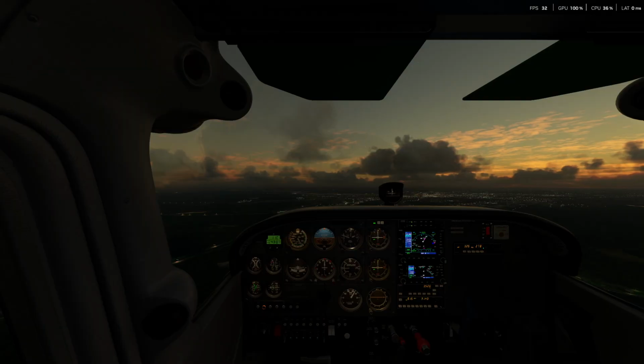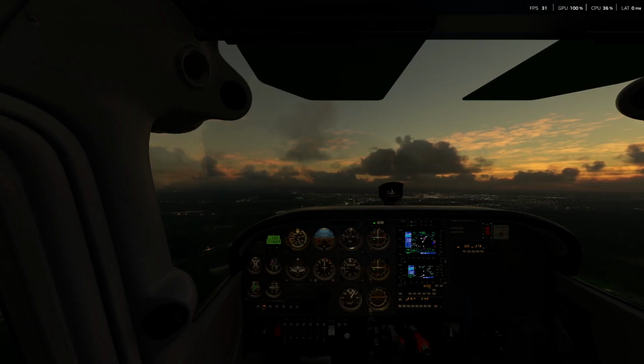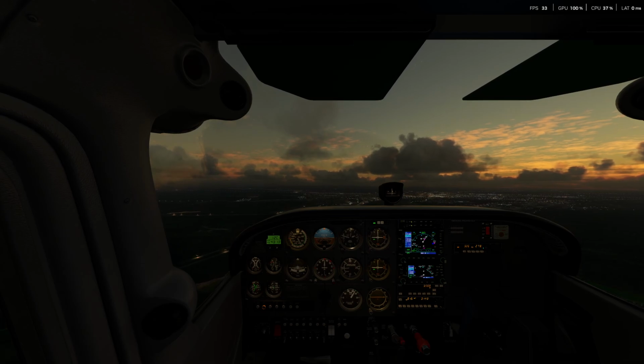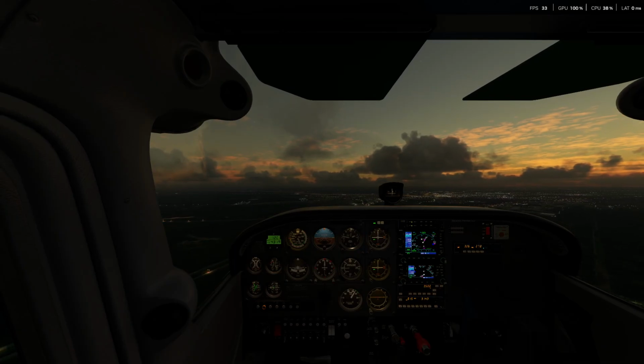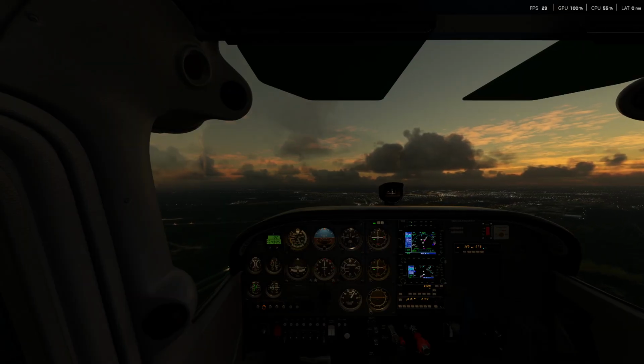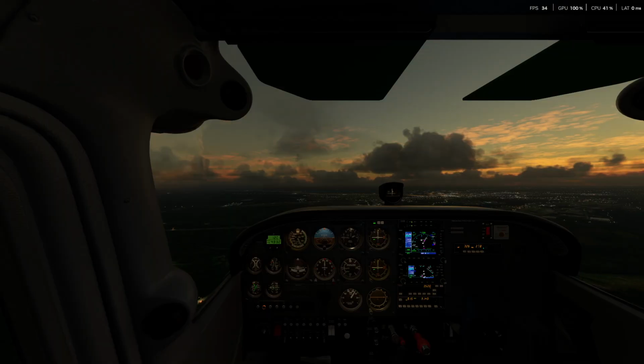You should be increasing the throttle just a little bit to increase the RPM. Basically, you want to make sure that everything's still working and that you still have that power available. The last thing you want is to get down low to the ground and not have that power there to keep it flying. So it's always good to do a little check. Keep that in mind next time and try to stick with it.